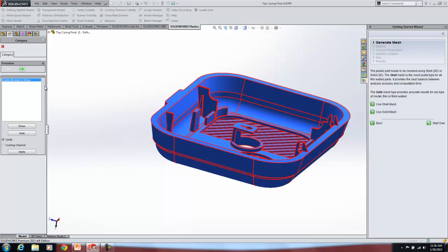So now I've got my body. So I want to mesh this body. So I'll select it and go to next. I can define the triangle size. Basically, this is the size of the element. Now I'll just set it to 10. And this is where I can set up the refinement. I'm going to set it to automatic, and I'll take my slider bar and move it all the way to 5. So this will give us the better mesh refinement. And hit my mesh button.